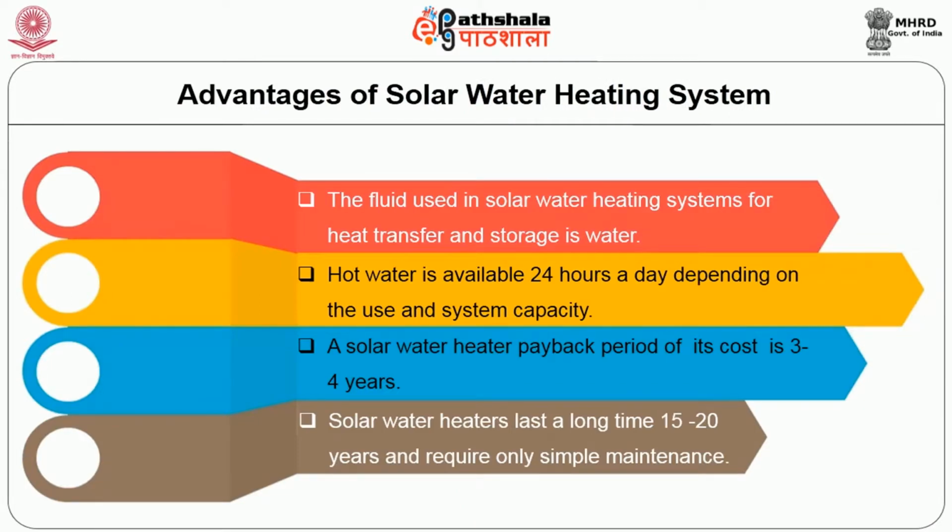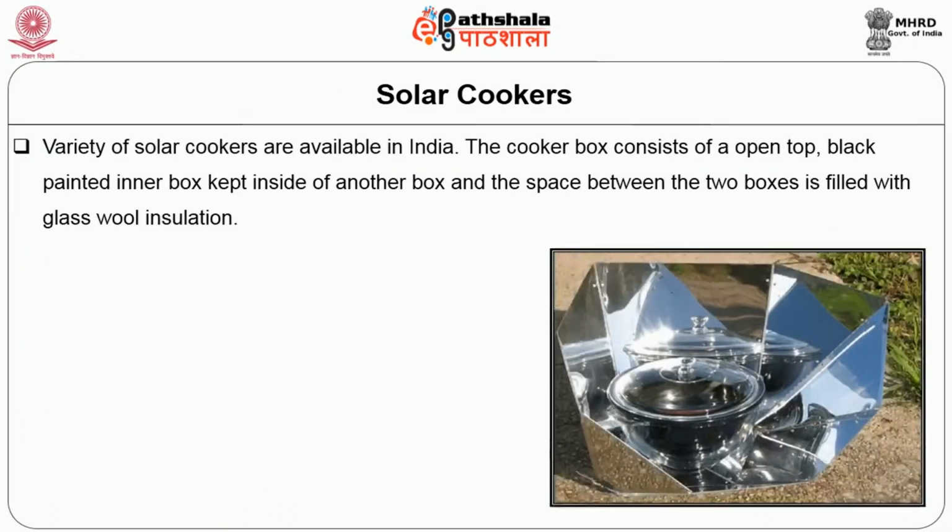The advantages of a solar water heater: the fluid used in the solar water heating system is water. The hot water is available 24 hours a day, depending on the system capacity. A solar water heater's payback period is 3 to 4 years. Solar water heaters last a long time, 15 to 20 years, and require only little maintenance.